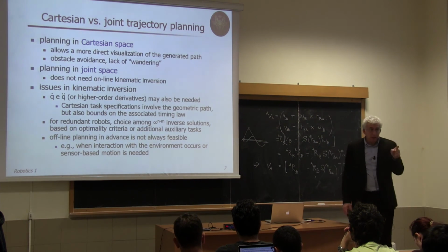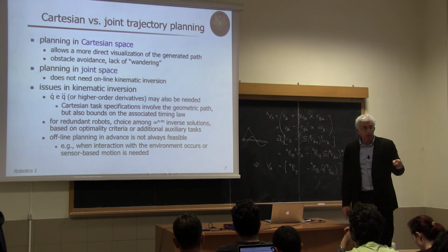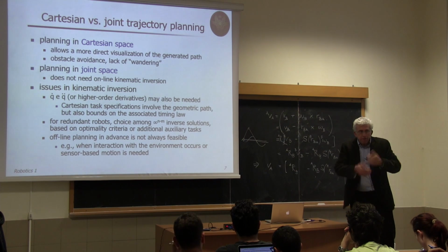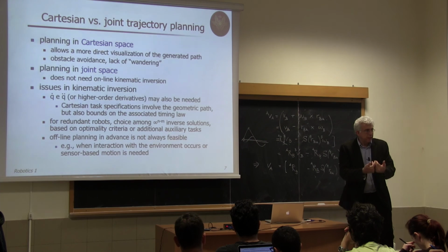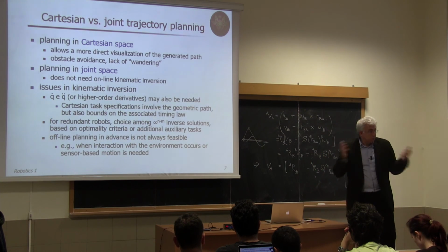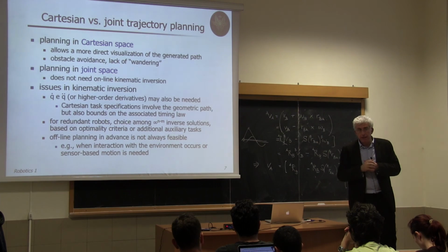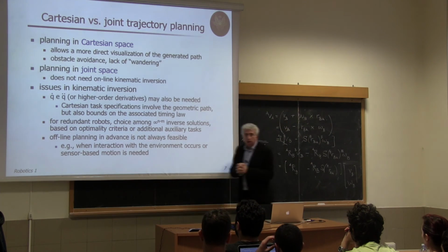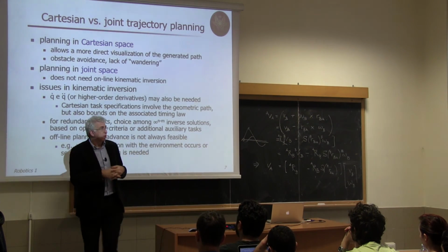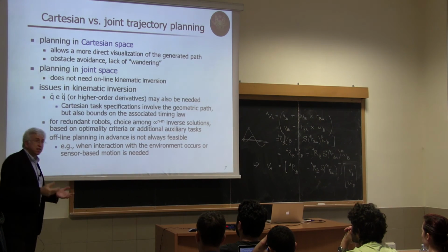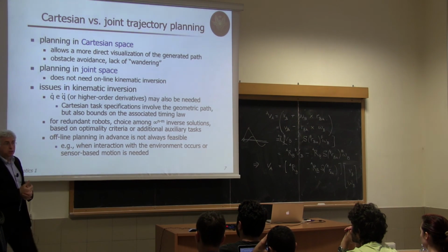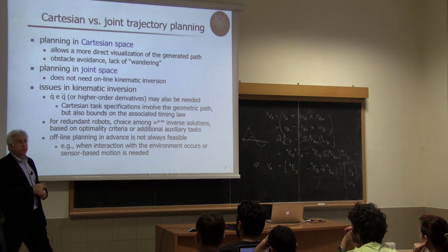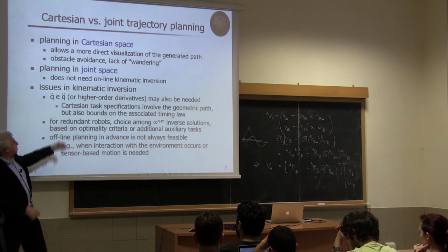But if you're forcing a linear path in the Cartesian space and the linear path is crossing the origin in this case, and you're inverting incrementally your motion in the Cartesian space, then when you're getting closer to that point, you will have the explosion of joint velocity like we mentioned. So you see that there are pros and cons of both things. Better visualization in Cartesian space, easy, less computation, and no problem of singularity when you have a trajectory reference defined in the joint space.